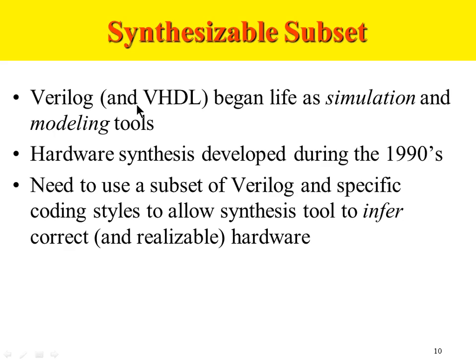To summarize, Verilog and VHDL began as simulation tools only. Later on, the synthesis process was developed, where these languages could be converted to a netlist and used on FPGAs or ASICs in hardware. But to do that, only a subset or certain part of the language can be used, where the synthesis tool takes the synthesizable part to infer correct hardware out of the Verilog design.